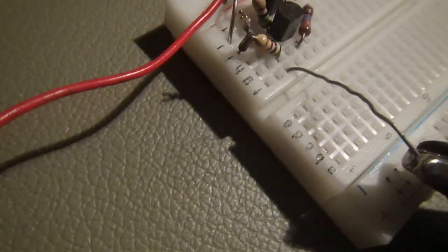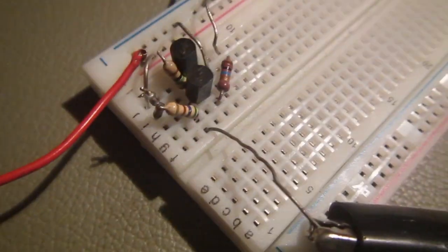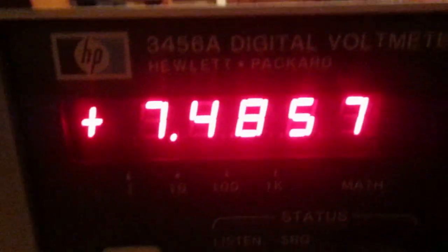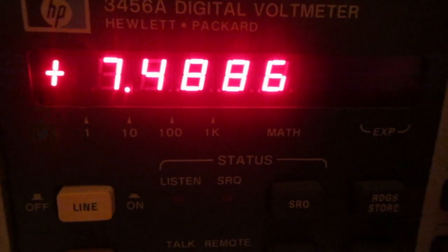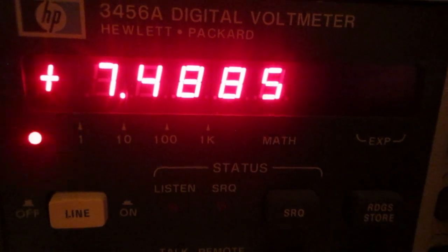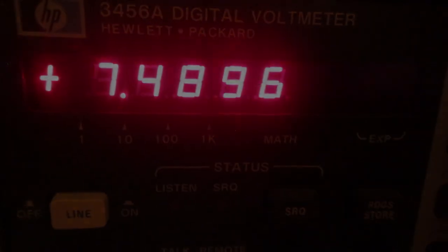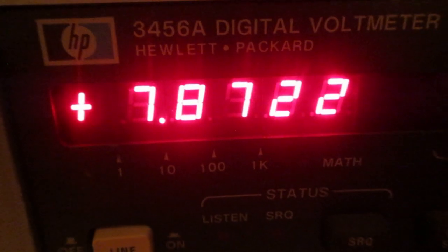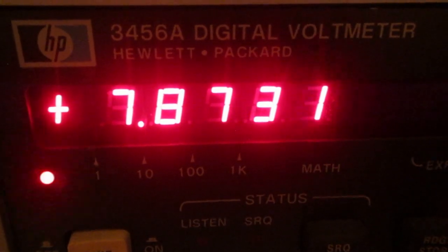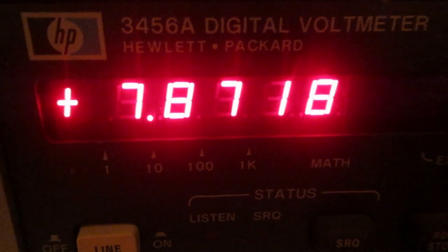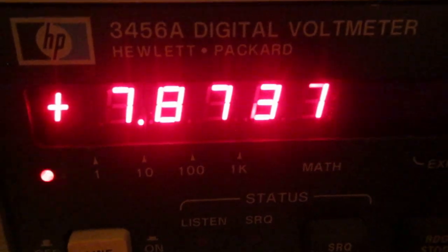So I found another 8.2 volt zener, this is an old Philips one, and soldered the resistor needed for the mod to it. This one needs almost 7.5 volts to leak the test current, which is half a volt more than the other one. And last test is a 9.1 volt random brand zener. This one needs almost 7.9 volts to pass the test current, but that's only half a volt more than the good 8.2 volt Philips zener.